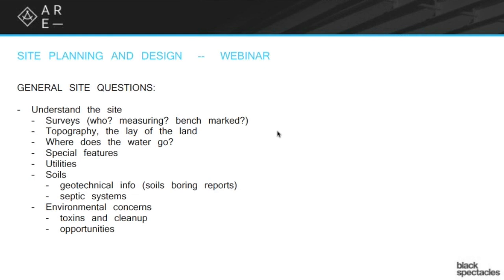Often it's just a visual thing, but they can test it as well. They will say, all right, this part is sandy soil with a little bit of clay in it. It's okay soil. Maybe you can get 2,000 PSF off that, pounds per square foot. So the geotechnical report is where you're going to find all that information. Can you think about what else you'll find there? Well, water table height you'll find.